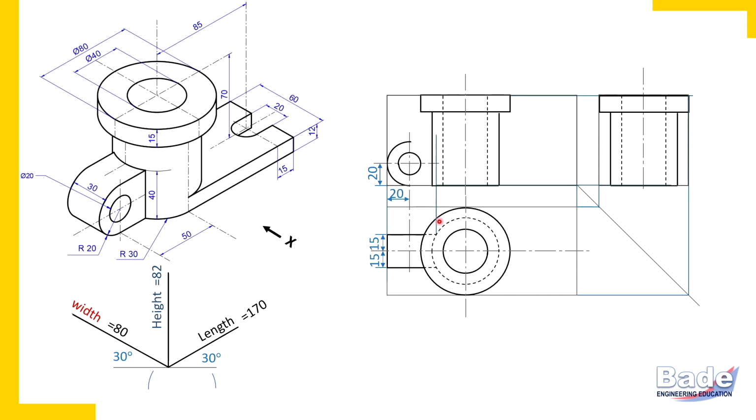Okay, so along this projector corresponding to this corner you should draw the edge, and the U-shaped block, that is this front U-shaped surface, meets the curved surface, and where it meets the curved surface it creates a sharp edge. So the exact location of that edge we have identified here. Watch here, by drawing the projector, this blue colored line, that is the projector from that sharp corner. So extend the edges of the U-shaped block up to that line, and along the projector draw the edge. So now this dark, continuous edge you have drawn here, this is actually this edge.